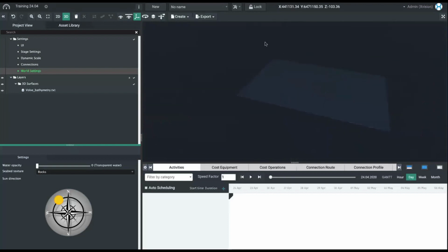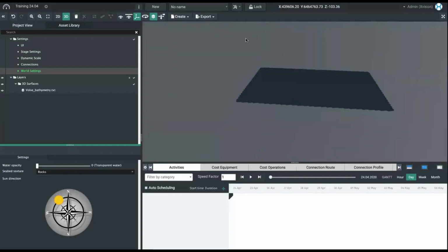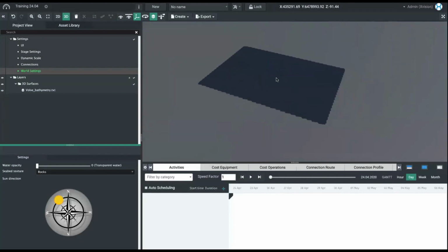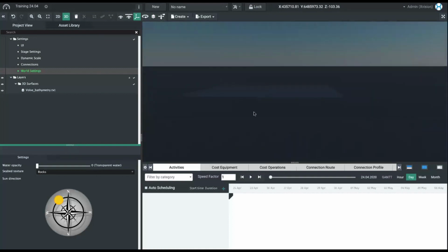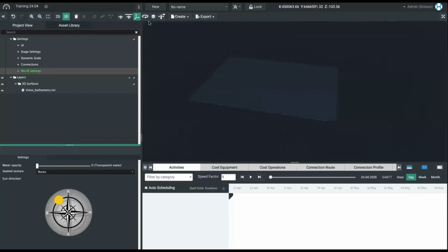If you don't want this, because if you have this visible, you will not be able to see underneath this seabed, you have to turn it off by clicking this button called reservoir. It removes the visibility of this indefinite bathymetry, so it allows you to see what's underneath. We had some questions around this. People who don't see their well data, that is because they have that enabled and you can't get underneath. It's like a big plate.